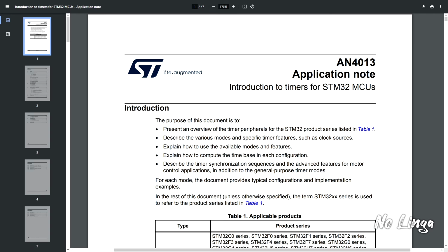Additional reference tools are available for download on the ST website or within the STM32CubeMX tool. So go ahead and download it. We're going to use these application notes. This will go over how to configure the timer settings and other features, especially the encoder. There's a special section on how to configure the quadrature encoder, and we'll go back over this in a little bit.